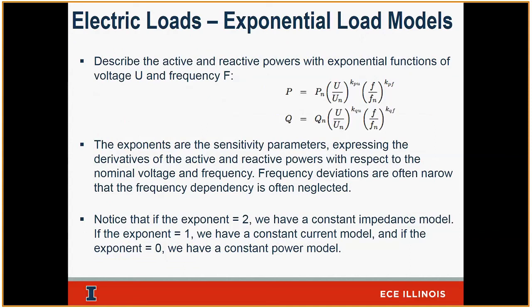The point of the exponential load models is to describe your active and reactive behavior as voltage and frequency change on the grid. Remember, we talked about how I'm being fed a specific voltage and frequency that comes from transmission, so I'm really at their mercy. Whatever voltage I get, whatever frequency I get, that's going to dictate the input to my loads. So I want to understand my behavior based on that voltage and frequency. We use these exponential models, and they use coefficients to tell me about my sensitivities. If the exponent here is 2, I'm using a constant impedance model. If the exponent is 1, it's a constant current, and if it's 0, it's a constant power.